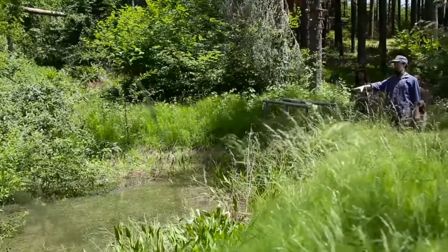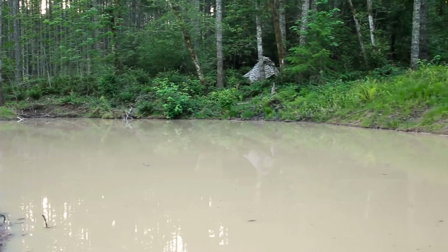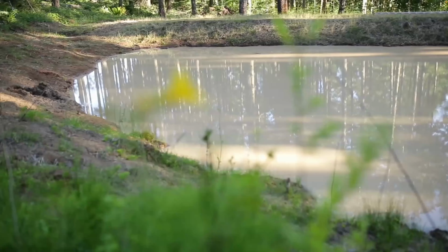Bunchgrass seed is a very good choice for the dam surfaces. You can also stamp in seed from native juncus and sedges. But the most important thing is to remember not to put any woody plants on the dam itself. So you never want to have trees or even any really woody plants growing on the outside or inside of your dam. If they are, they can put their roots through to reach the water, and that'll create a channel for water to flow through and compromise the dam.